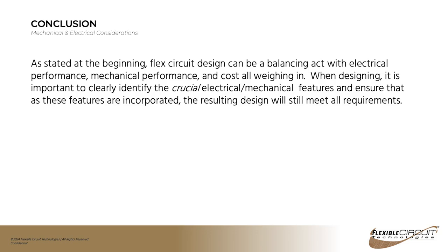So really what you're going to find is flex circuit design is going to be a balancing act. Your electrical and mechanical engineers may not get exactly what they want. Everything has to weigh in and everything has to work. And so you may find that you may not get absolute flawless electrical performance in order to get the mechanical features to work, and vice versa.